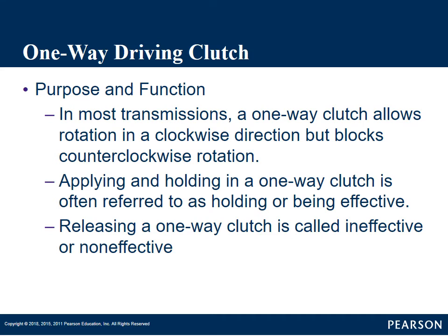Now we're going to talk about one-way driving clutches. Again, we talked about this on overrunning pulleys, on alternators, and our starter drives. This allows a rotation of a device one way, and in a transmission that's usually clockwise, but locks it in the other way, and in most transmissions that's counterclockwise.